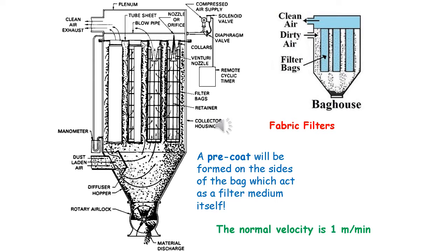The upper end of the bags is closed and the lower end is attached to a hopper, where also the inlet of the flue gas is located. It drops out particulate matter in these bags, which settles down into the hopper, and cleaner gases go out from this fabric filter. The framework housing the hanging bags is provided with an automatic shaking device for cleaning the bags of the collected dust.